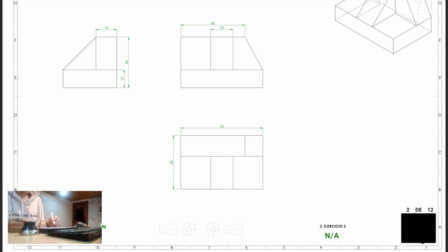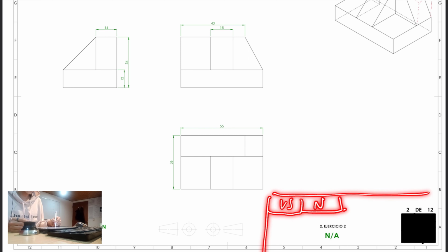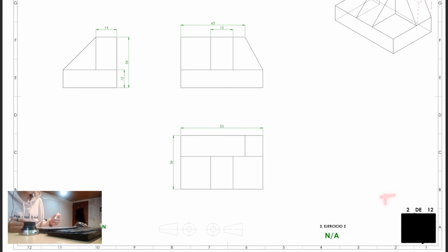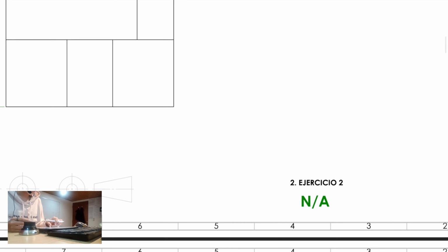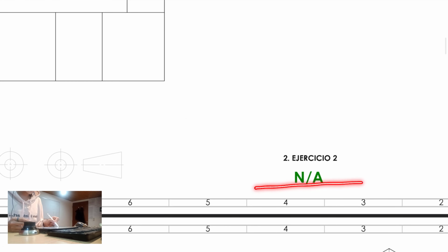Usually, within that box, you place, for example, the unit system, the name of the person who made this engineering draw, the name of the part, if there is some tolerances information, some manufacture process, some notes, whatever. The material, of course. He always places the material right here, so I know that this was meant to be, I don't know, aluminum, copper, steel, but please place that information on that box.